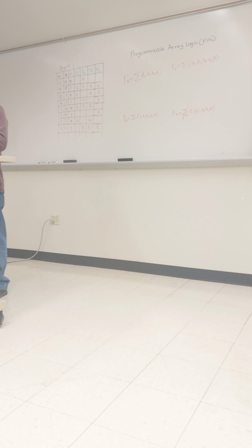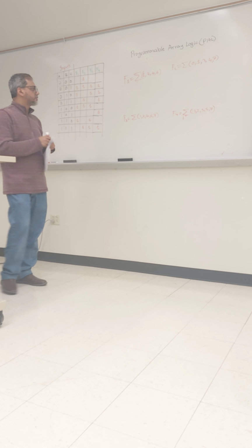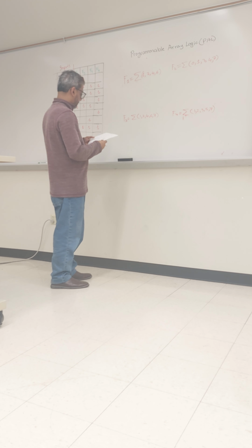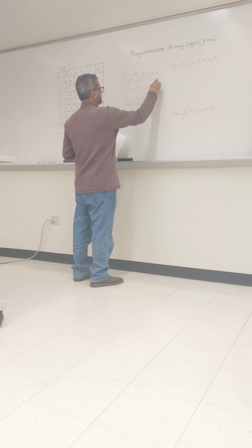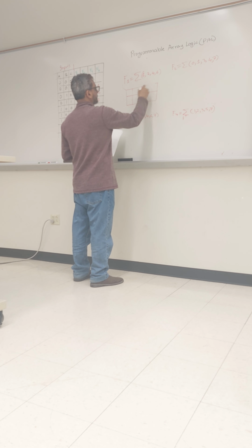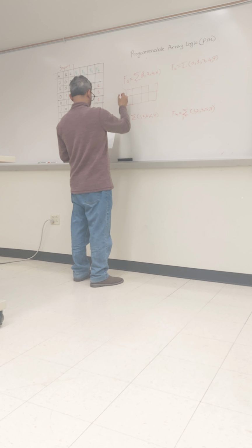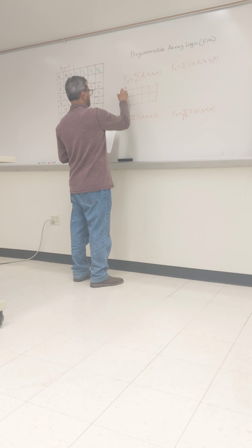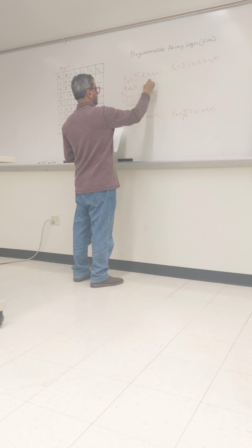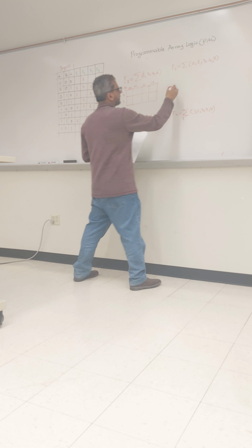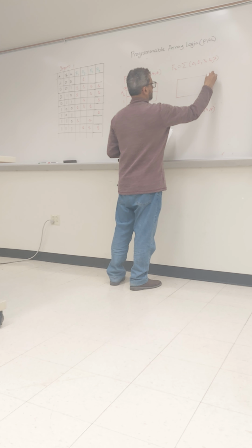What we can do, we can use the K-map to minimize. That was the very easiest one, right? Draw the K-map so that we can find the functions. If it is the K-map for this one, this is A, and this is BC: 00, 01, 11, 10. Draw the K-map for every function.